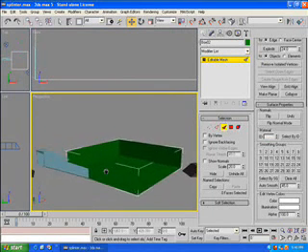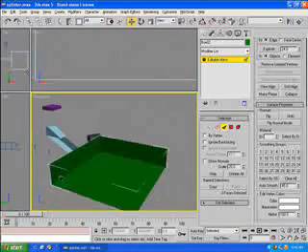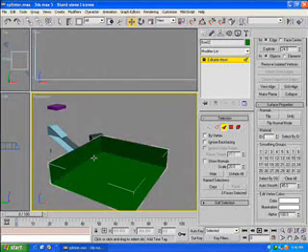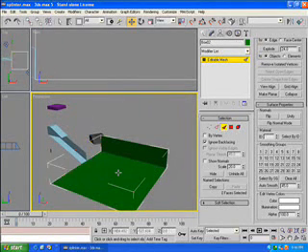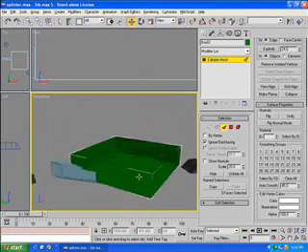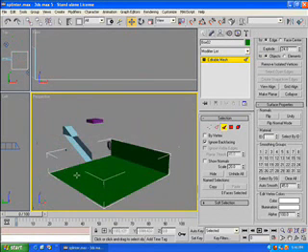And we're actually going to want to delete the 2 faces that are facing the entrance to the tunnel. So in face selection mode, we're going to turn on ignore backfacing, select those 2 faces by clicking the control key and clicking both of them, and press delete. And now we have deleted the face that'll be facing the entrance of the tunnel.